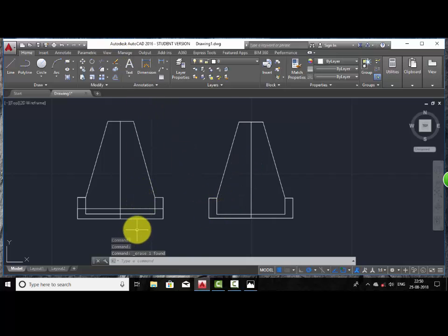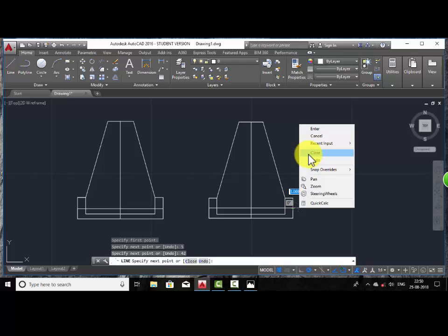And for the middle portion again I press line enter, because after escaping, after closing, all the commands are erased from AutoCAD. So I just press line enter and put the amount, that is 5 centimeter. Again the baseline is drawn. Here at the crossing point just please click OK, so that the 42 cm is showing, and press enter. For the extra line the same procedure is followed, that is closed.